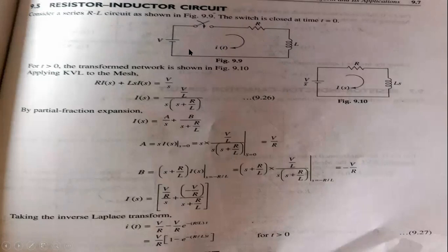So this is the basic, simple circuitry, a series circuit, where R is connected in series with your L, and the circuit at present is open, the switch is there. Whenever the switch closes, definitely current will flow through the entire RL circuit, and the voltage is across the components R and L. Whenever the switch is going to close, before closing, t is less than 0, that is nothing but 0 minus.